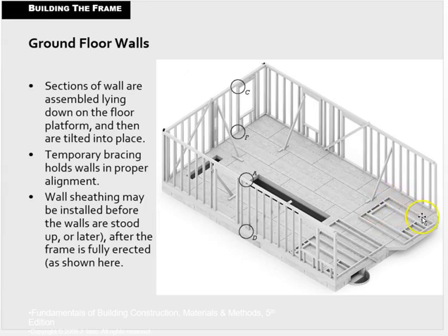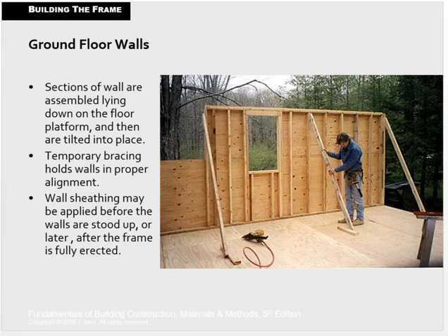Sometimes it's put on the floor here, but it's heavier. If it's easy to access the outside of the frame, then the wall sheathing would just go on later, which it typically does. And this looks like a situation where the wall sheathing might have been put on prior to raising this. Looks like he's working with the brace. Looks like he just put this wall up, so my guess is the sheathing was put on and then the wall was stood, much heavier.